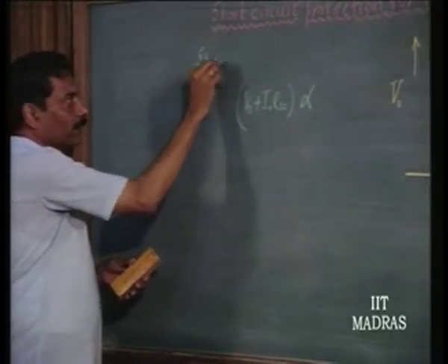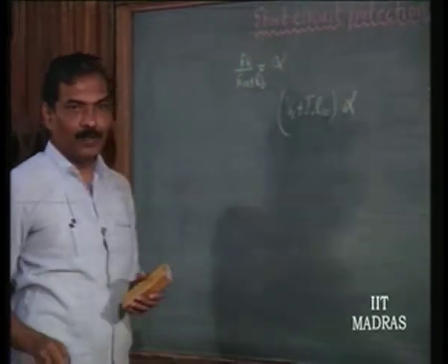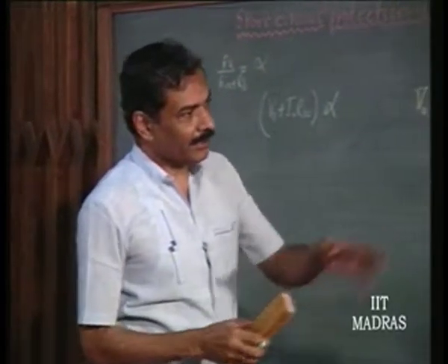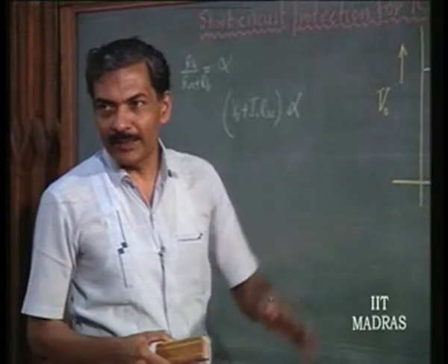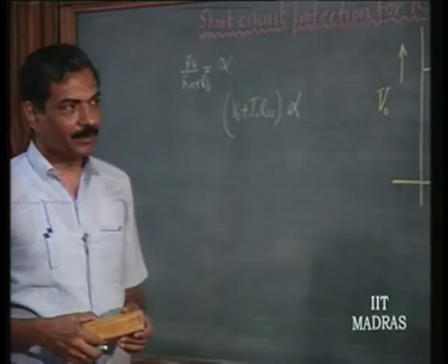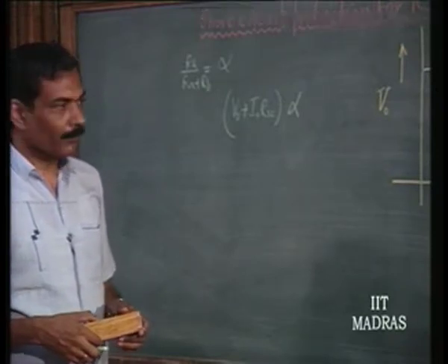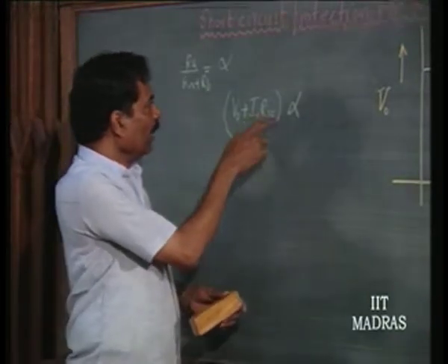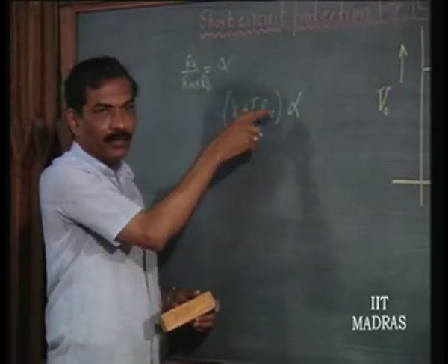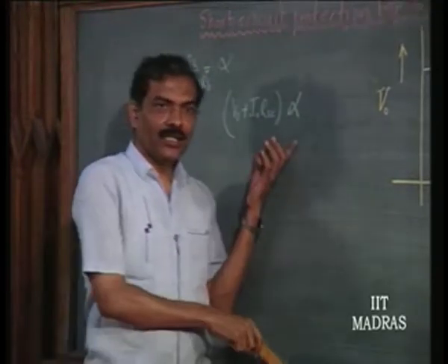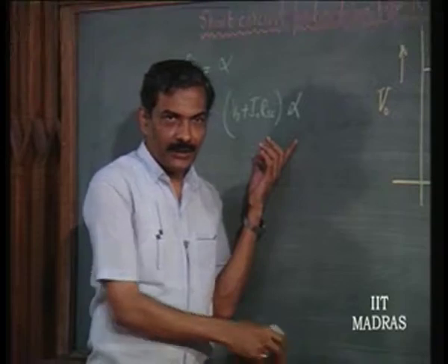Yeah, RA and RB should be large. Just as we select R1 and R2, we are also going to be taking care not to take away too much current from the load. Okay. So, alpha is nothing but RA by RA plus RB. That is a small enough voltage which we can use,